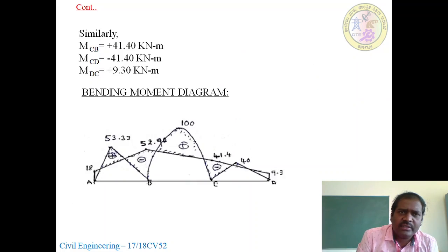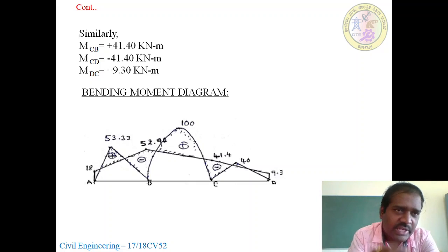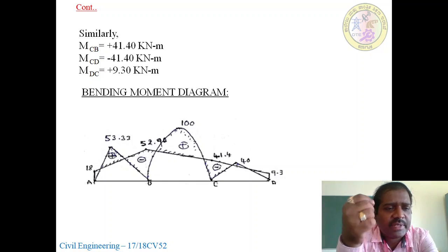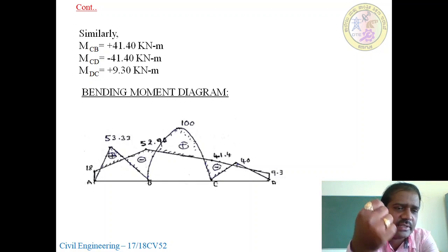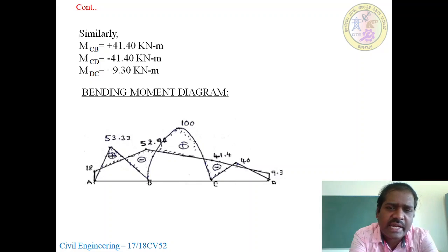So you will get all the bending moments, all the moments. So draw the bending moment diagram. See here at A. Check whether the standard directions are matched with the signs of your final end moments or not. What do you understand by standard directions? We have a standard direction for AB, BA, BC, CB, CD and DC. The first one is anti-clockwise, then clockwise, anti-clockwise, clockwise, anti-clockwise, clockwise.